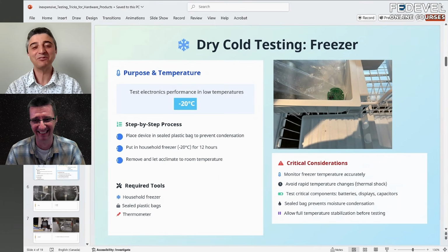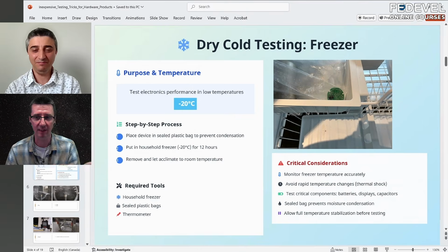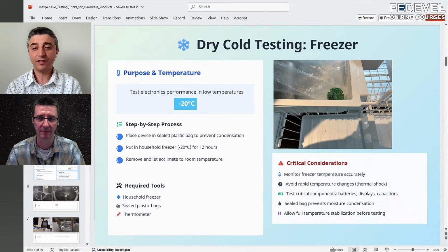Oh, interesting. It seems like you have very good stories. Yeah, I'm pretty sure. We had a problem, especially one with, what was it, the Ethernet chip? It was, and we found out it was actually a silicon problem. It was never fixed on that specific silicon. We had to use a compatible chip, and then it was fixed. Yeah. And don't underestimate these kinds of testing.